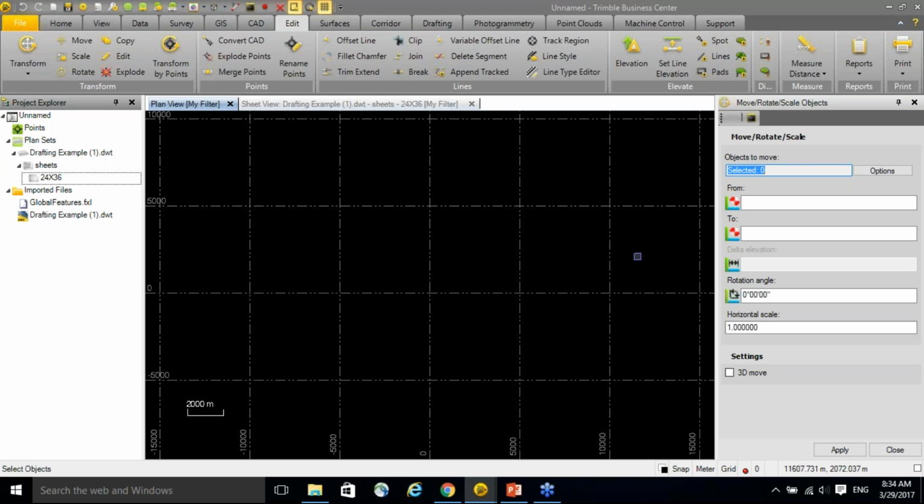Mike asked another good question. If you don't have an existing FXL file, which is the feature code library, can you import feature codes from another source? That's a good one. You want me to take that one? Yeah, sure, go ahead. There are a couple of methods. If you're using Excel, you can copy and paste from CAD into Excel and then use a custom import for the feature definition manager. It lets you import a CSV file with setup of the columns that you want to include. There's also third-party software that does it that you can contact me about outside of this. But there are ways to do that.